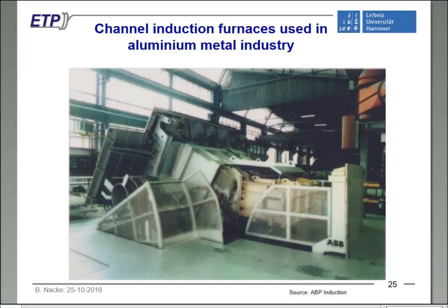This is a quite low-powered system. Each inductor has only 500 kilowatt, so 2 inductors is 1,000 kilowatt per furnace. I have some information that these furnaces are also supplied with inductors of already 1,500 kilowatt. I will show that in my next table.